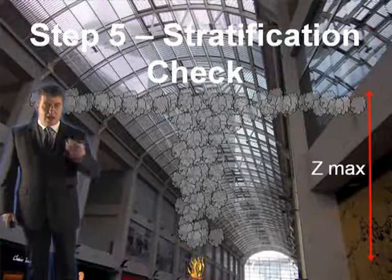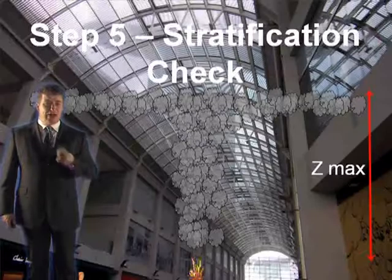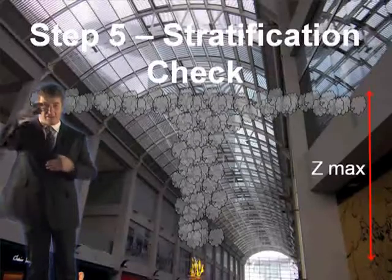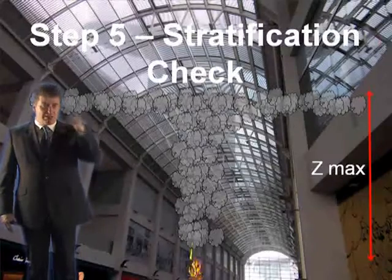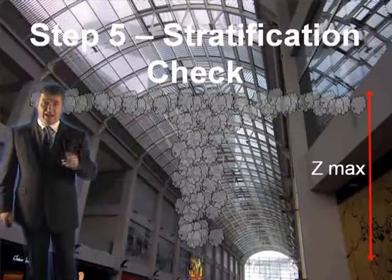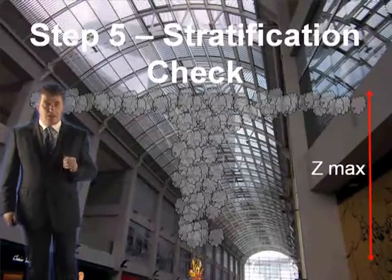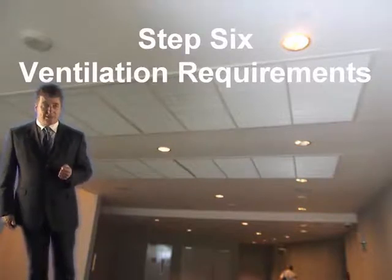Now before determining this, we have to consider stratification, and this is covered in step 5, the stratification check. Now in this building, due to having such a low clear layer height, we've got 8.5 metres, stratification is not going to occur at that level. You're looking at 8 stories high, you've got to look at quite high figures for stratification. So in this case, you can actually ignore step 5, you don't have to carry it out. You can move straight on to step 6, which is determining the ventilation requirements.